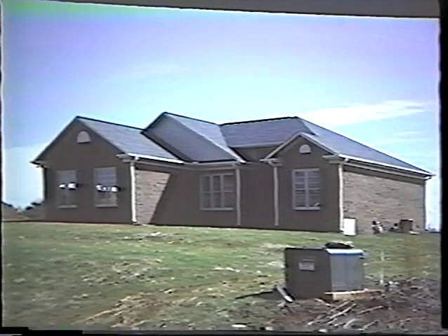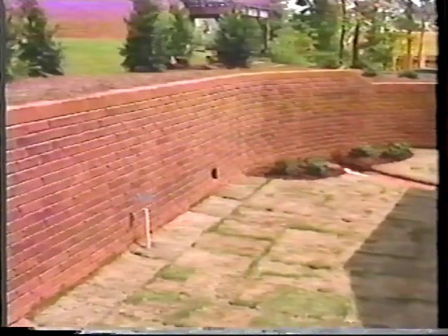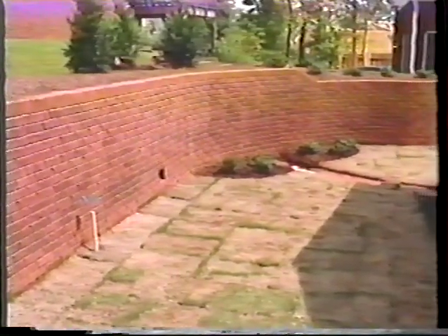Expansion joints are usually not necessary in small to medium-sized houses. However, if there are large expanses, many returns, or different support conditions, then expansion joints should be used. Expansion joints are usually placed in walls over 30 feet in length. They are installed at corners and at offsets or returns in long walls.